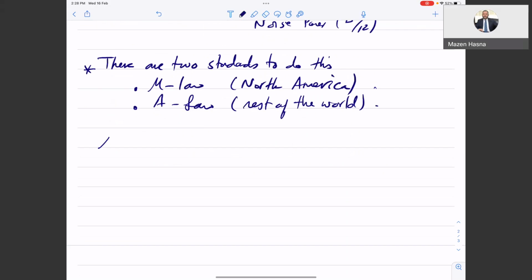What's the mu law? In practice, you don't use larger delta and smaller delta. You use a small trick. Before you quantize the signal using equal deltas, you compress it. If it's large, you compress it. If it's small, you enlarge it, so that you introduce some harmony among the different parts of the signal, and you do the opposite, of course, at the receiver. Okay. So the mu law, we compress the signal according to the following equation.